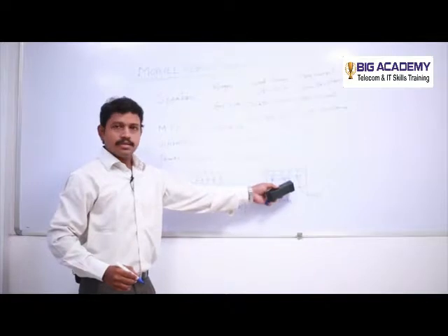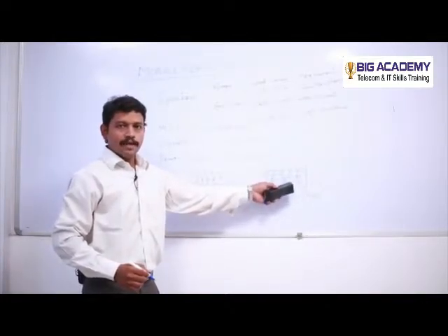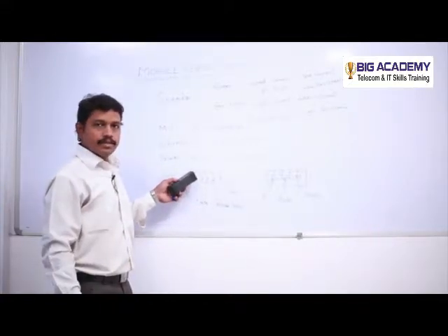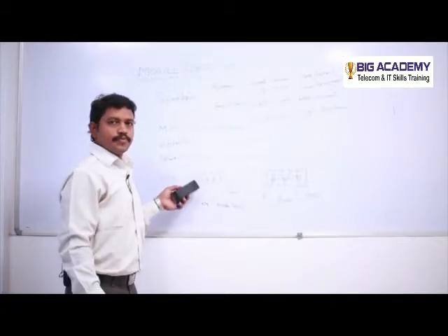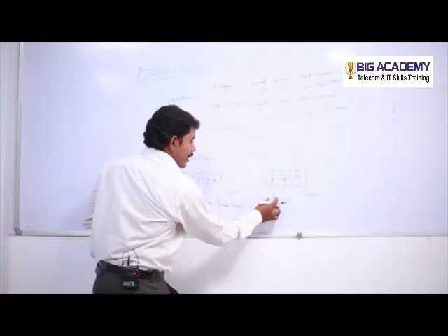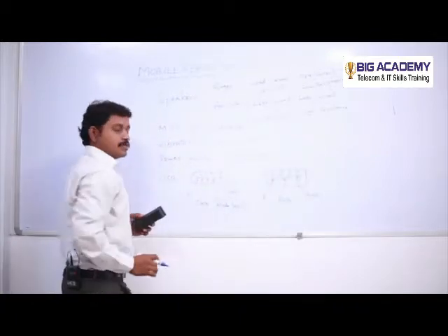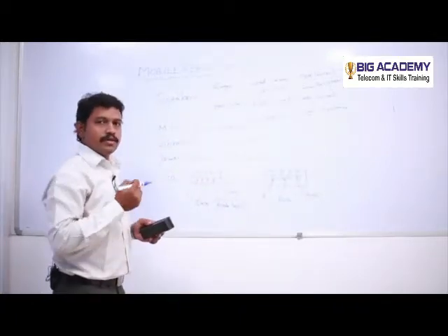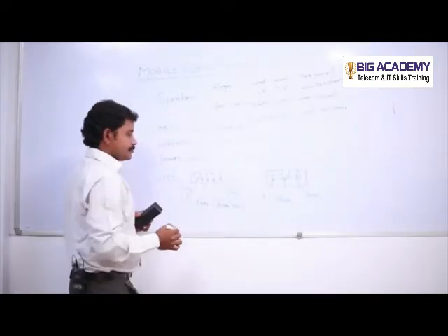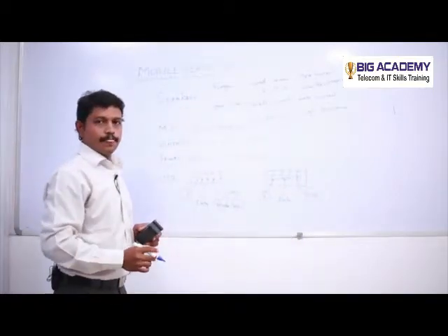Right. So this is the pin USB A connector, which has been connected to the computer or laptop devices, and this is a pin diagram, pin connector, which is connected with your mobile. So if you want to check whether the USB A or B is working or not, you have to check with the help of a multimeter. You have to check the voltage and the ground. Here, voltage and the ground and nothing else.